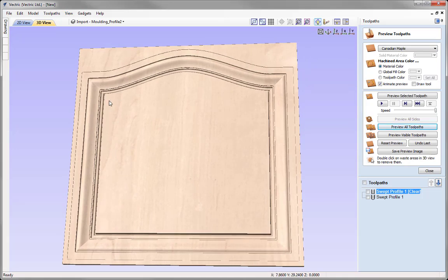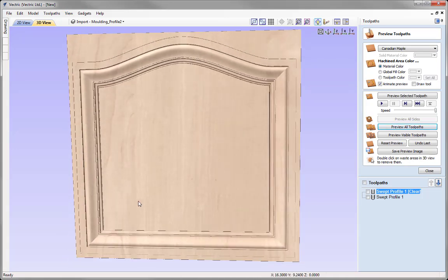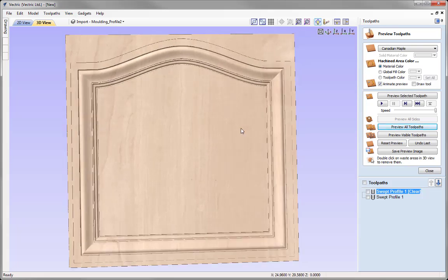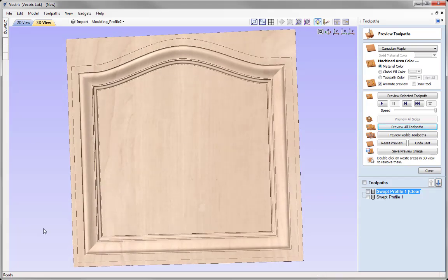Now you've got to be wary with this in case you have some tight internal corners, and this may cause errors with this toolpath technique. With most straightforward mouldings such as frames or mouldings that we were looking at earlier, you shouldn't really have any issues here. One other thing that we might want to do is actually swap which way the cross section is being hung from the rail.